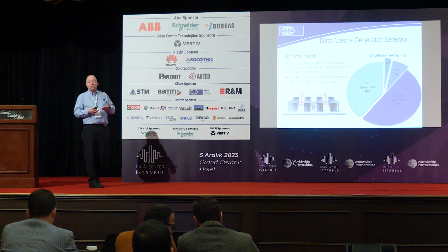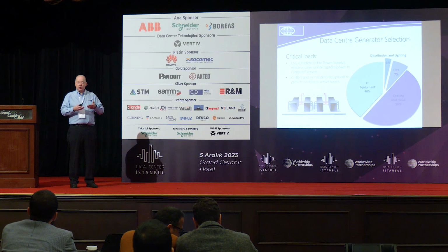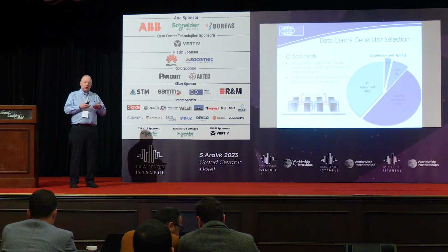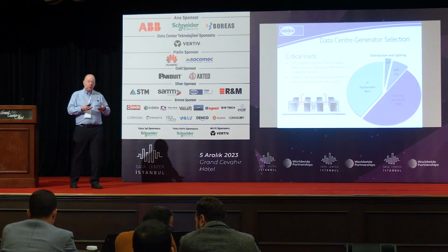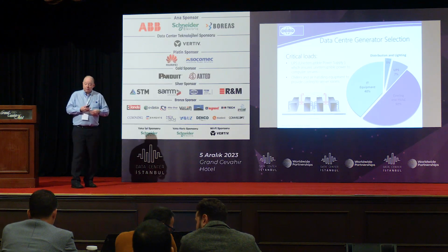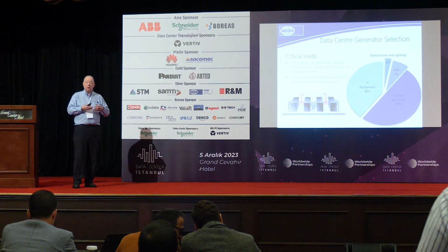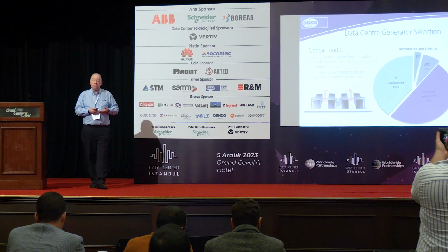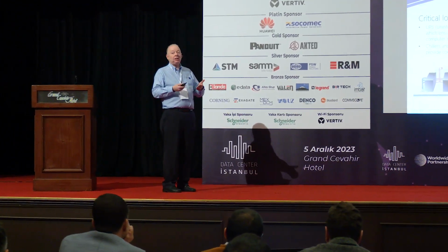So that presents some different issues to the genset itself, especially because server loads in many cases have high capacitive effect, probably a bit more non-linear or distorting load. And in a situation where a UPS has gone into bypass, the genset needs to potentially take a large transient load step.